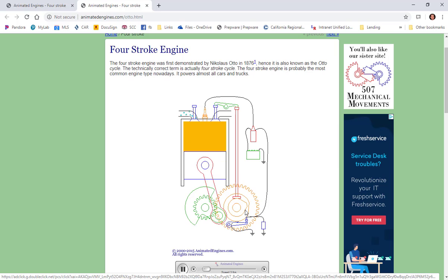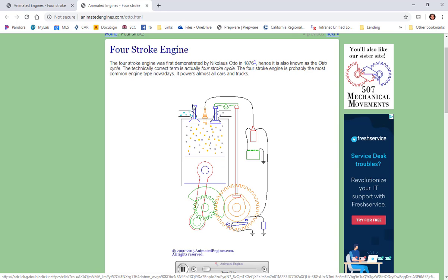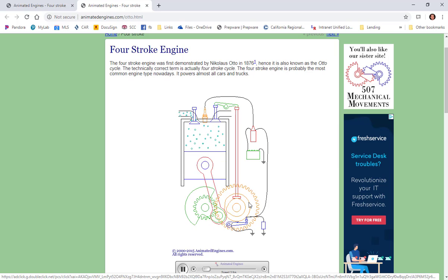But the camshaft is going to only go around once to make that happen. And what you can't see is the camshaft actually goes in the middle, and it's got a little lobe that's also doing the same thing over here, but they only show it half. And this is a battery system, so we can actually kind of put it all together. There we go, the cam is kind of working. So when those open up, that's going to fire. So the point I'm making is this goes around twice, this goes around once. So the camshaft is directly tied to what's going on with the valves and the spark plug.